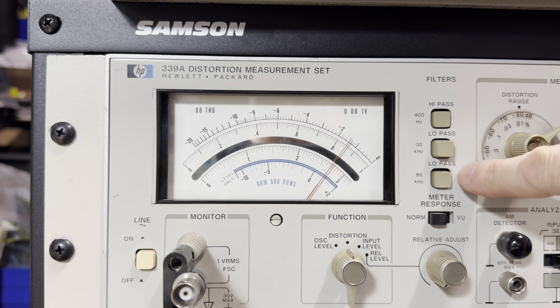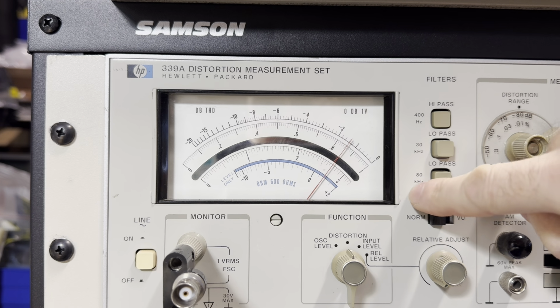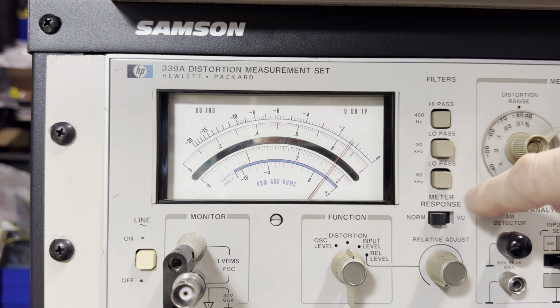And what we've done, now remember that we're measuring a signal at 1 kilohertz, and we've put in a low pass filter at 80 kilohertz. So this effectively is removing components out to the 80th harmonic. We're not necessarily concerned with components that high out, because they're going to be so insignificant, as the harmonics go from a signal, they tend to be smaller and smaller in magnitude. So an 80th harmonic of 1 kilohertz is going to be so small that it's not going to be contributing to a meaningful measurement, even when the filter's not there.